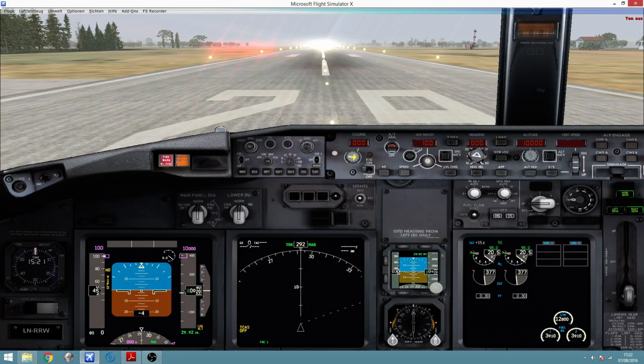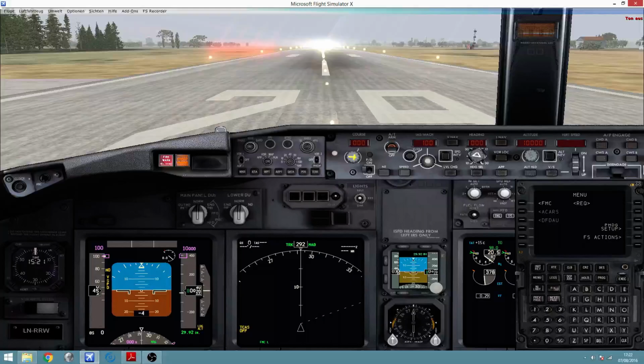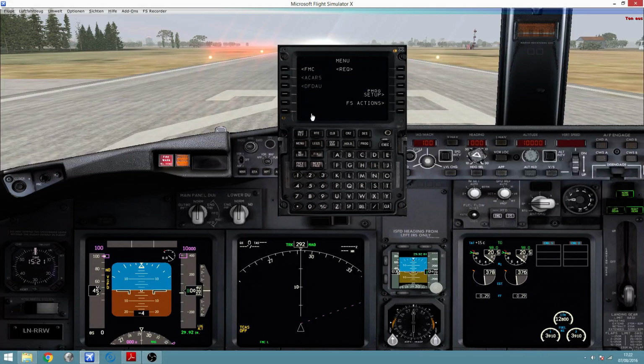Good. So before doing anything else, it says we have to configure our aircraft. It says before doing anything else, open your FMC, your flight management computer, by pressing Shift 3. By pressing Shift 3, I open the flight management computer, which is this thing that popped up here, and it says we have to go to Setup, Aircraft, Displays, and go to page 9 out of 9.